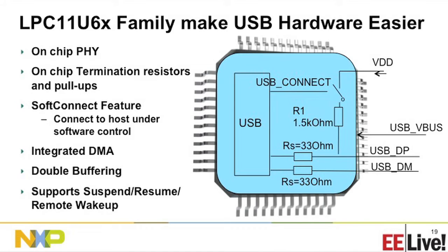It has to drop down to a suspend mode where it consumes much less power from the host. This is especially important for bus-powered systems. Normally, a full-speed and low-speed USB device consumes 100 milliampere as a unit load. But in suspend mode, it has to consume 500 microampere or less.